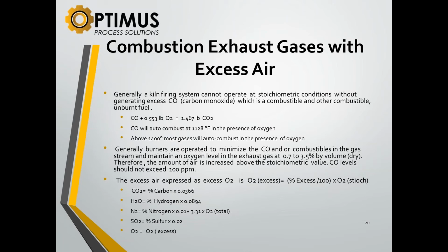And the CO can be measured with a handheld gas analyzer too, right? As long as it's measured in the kiln. Measured in the kiln, but not after the seal. Not after seal, not at the exhaust hood. Right. Because then you have all sorts of other leakages. You got leakage everywhere. Right.